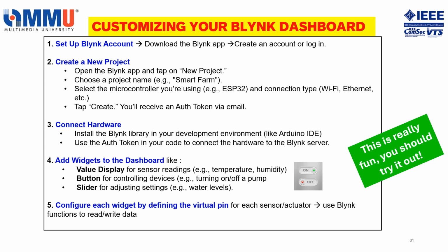Configure each widget by defining a virtual pin for each sensor and actuator. Use Blynk functions to read and write data to these virtual pins. Customizing the Blynk dashboard is a really fun activity, and you should try it out.